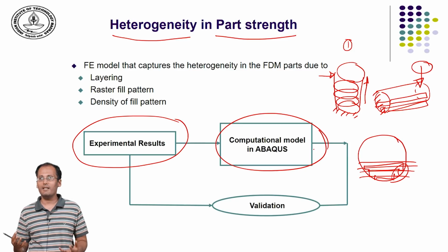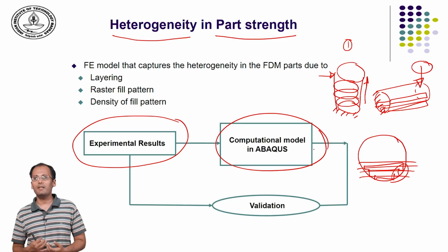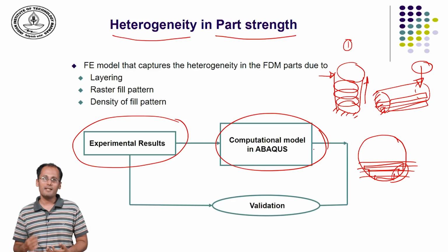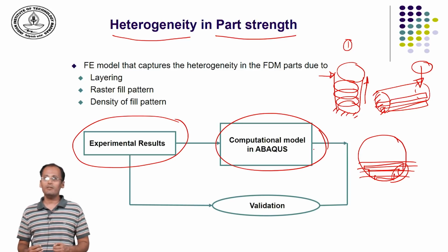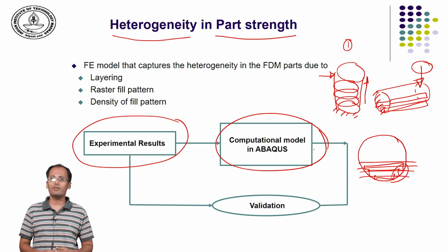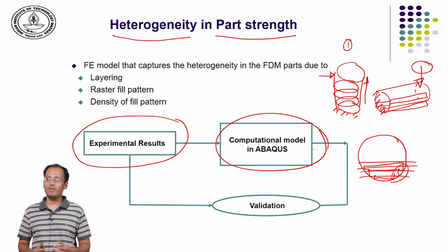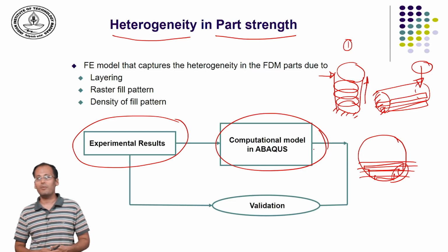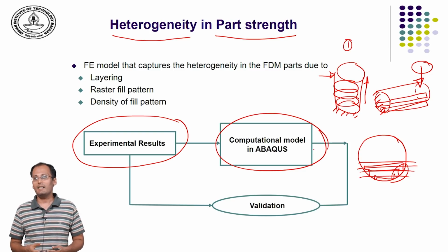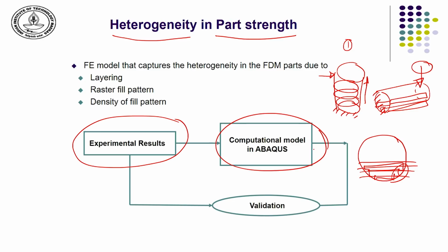So, unless I reflect this in my design, I may not be optimally designing a part which is going to be additively manufactured. One cannot use a computational model which has been used for, let us say, understanding the mechanical behavior of an injection molded component. So, we need models that will reflect how the additively manufactured component will behave.